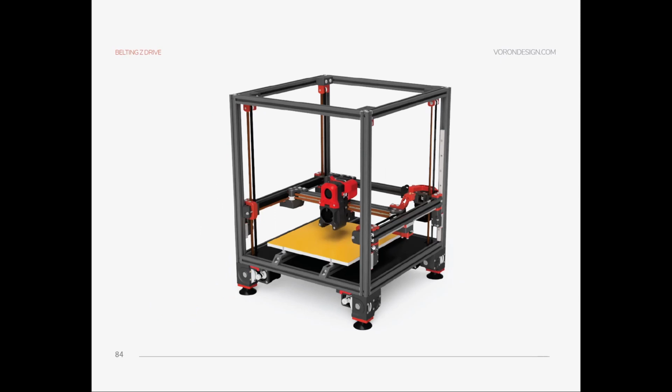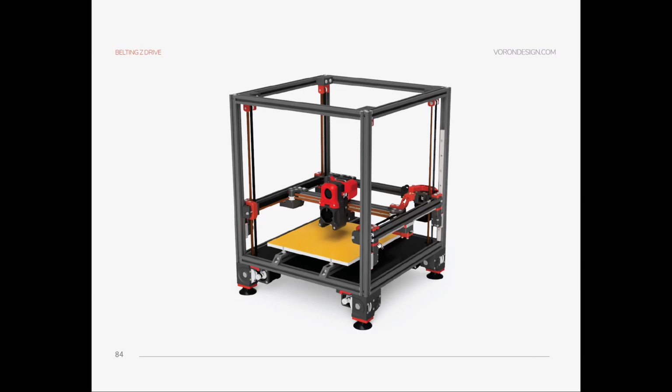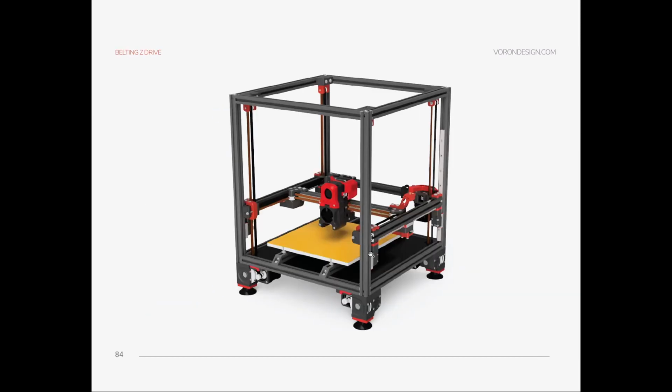And for the bottom part, you are placing this bottom. For the bottom parts, also install your Z belts, and the belts need to be flush in here. After that, install these bottom parts on your rails while your gantry is not installed on your frame.